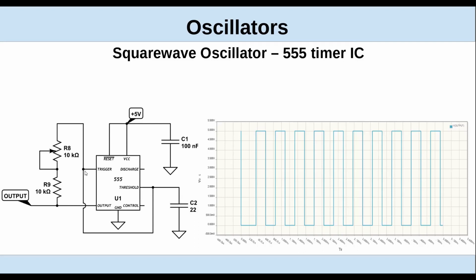So however long it takes to charge this capacitor affects the period of the waveform. It's set internally with the trigger value. So as it starts charging up, when it gets up to the trigger point, it discharges it and then starts all over again if you configure it as an astable multivibrator.